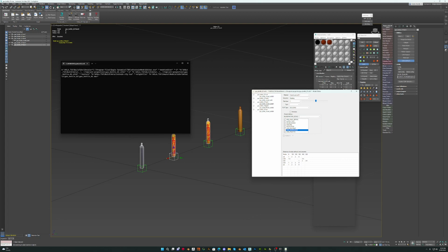Then we move to LOD 2. So we'll just check our distances, 600. Okay, go to LOD 2. So we'll do 500, 600. And for the distance, so this is the max distance, I would say 1200 to maybe 1300.